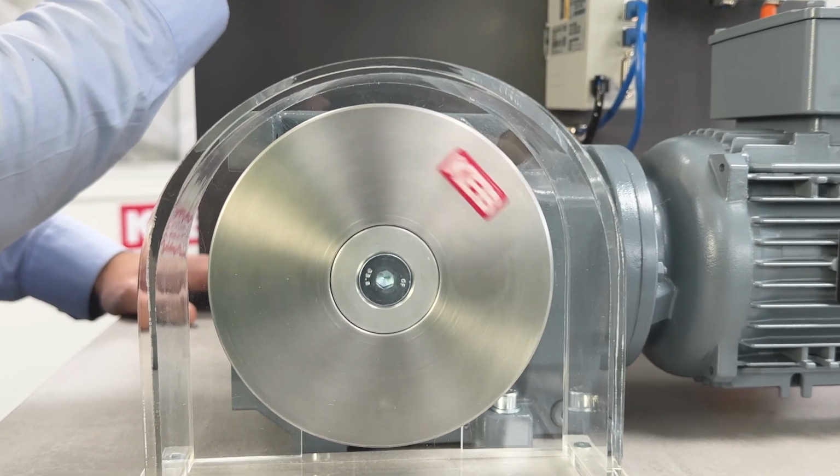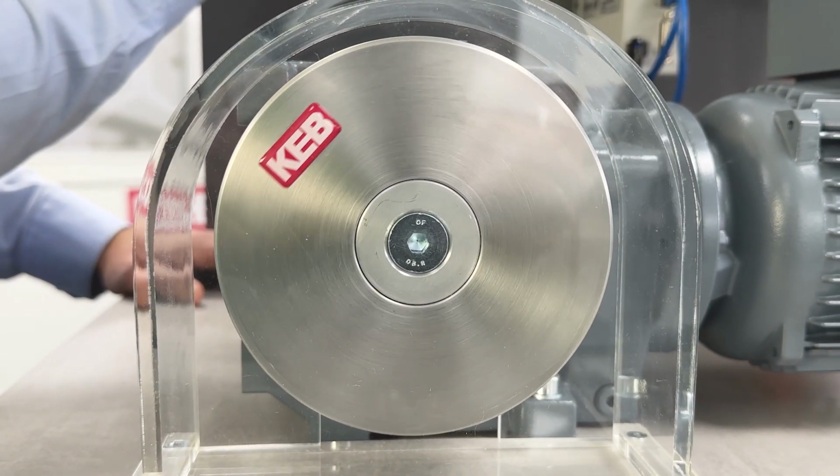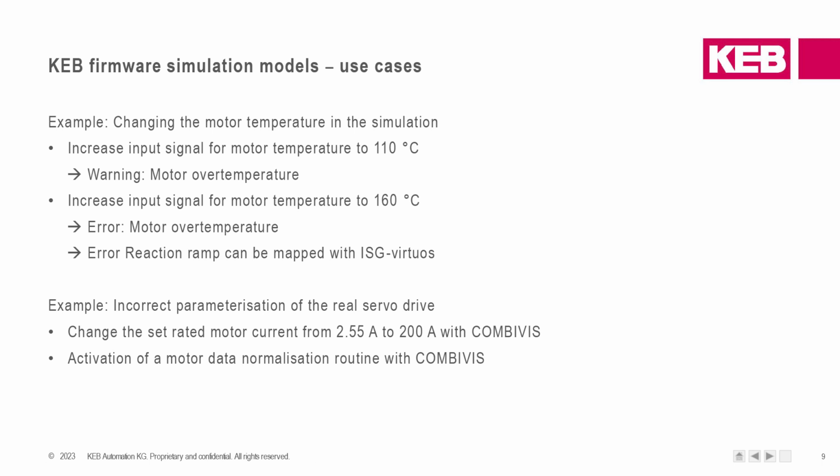a given drive. Also, we can set up some use cases and scenarios to get the engineering PLC error codes, wrong mapping behavior on the fieldbus programming of the EtherCAT communication, some error detections with wrong motor parameterization, and some specific error and fault reaction ramps during some drive-specific scenarios. With the help of this practical demonstration, I will show you some details of how the simulation models can work and how deep our simulation is with the help of our firmware simulation model.